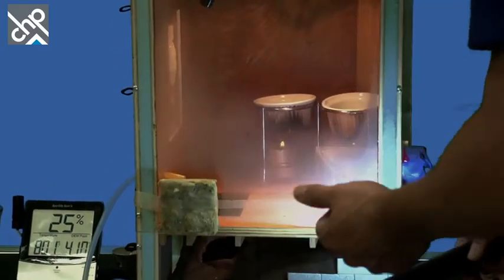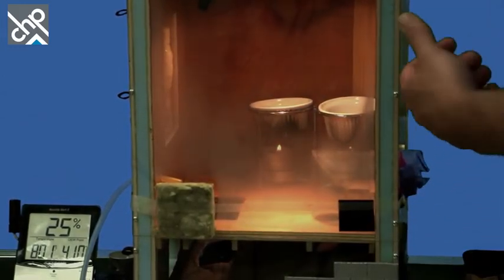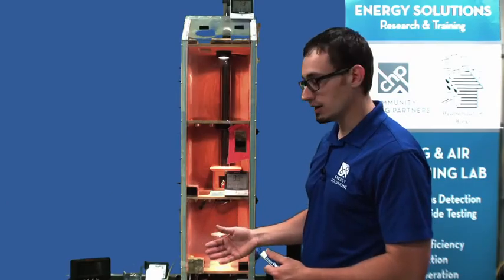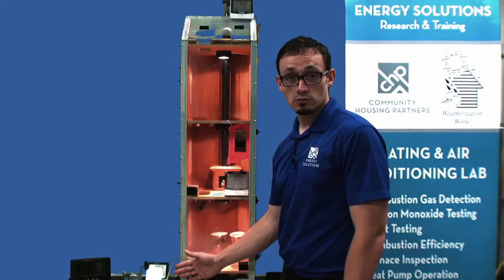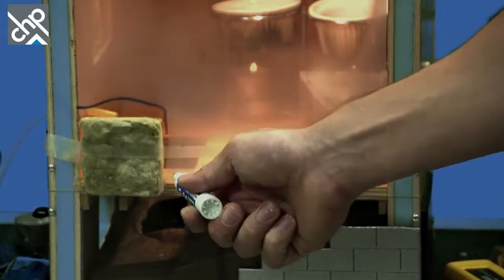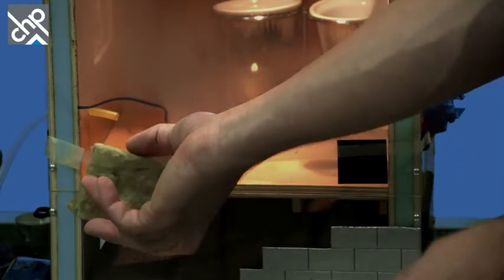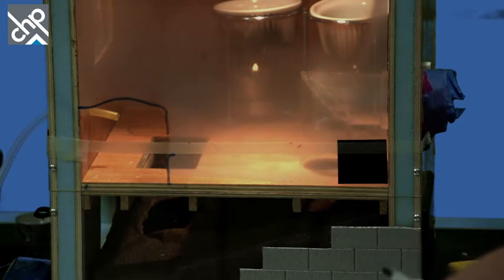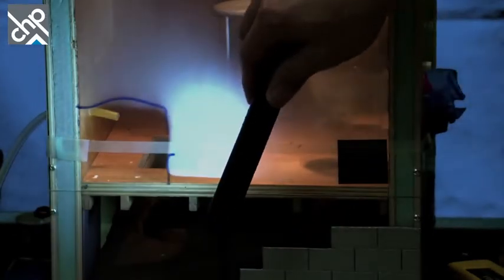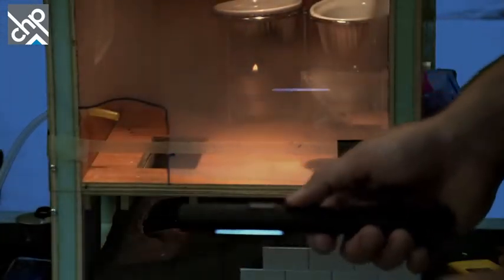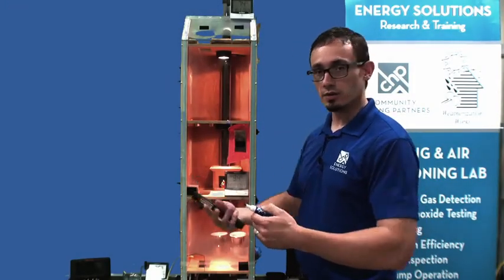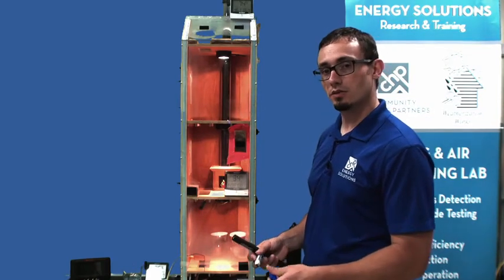I can touch it, I can move it. This is exterior insulation. So if you think about what that exterior insulation is going to do, the heat's trying to move in which direction? From inside to outside. So is this insulation going to keep that surface warmer or cooler? Keep it warmer, right? So if I draw a little outline here around where this was, I'll take this down, check that out. No condensation whatsoever on that surface. Why is that? Well, again, because of my dew point temperature, that insulation kept that surface above the dew point. Therefore, I didn't have any condensation present on that surface. Okay?